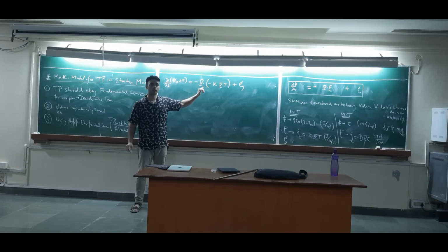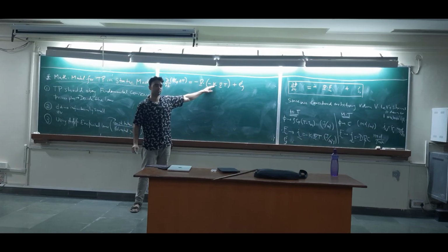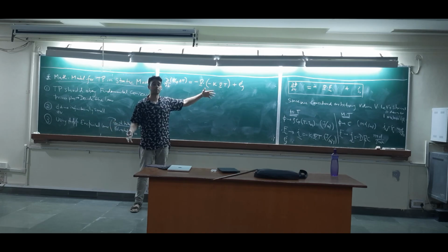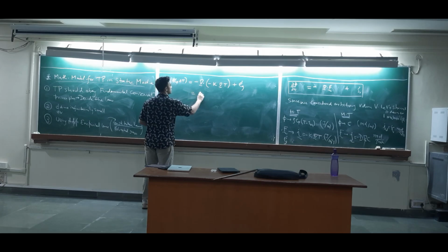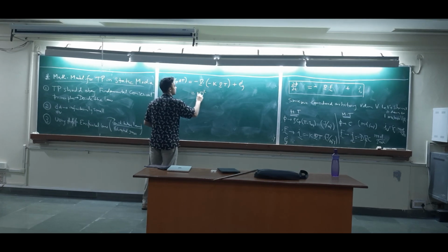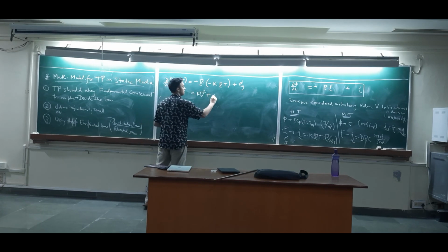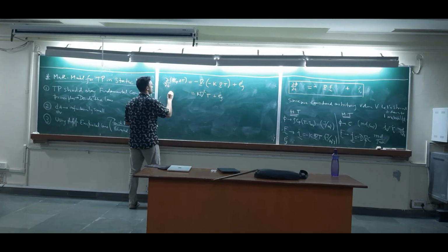Right? Now we will assume for simplicity that K is constant and uniform. Are constant and uniform the same thing? No, right? Here uniform means it's the same at all locations, but in the exam it could be non-uniform also, right? K del square T plus E gen dot equals rho Cp dou T by dou t.